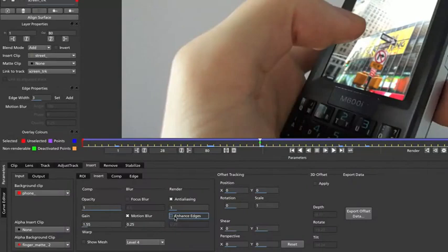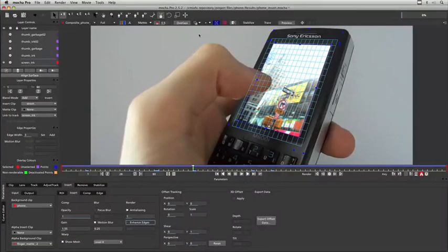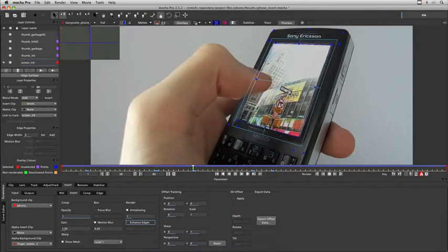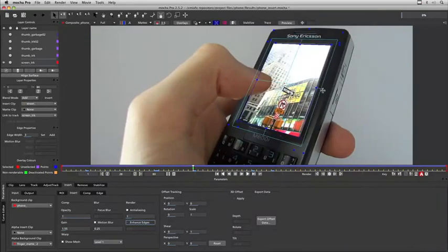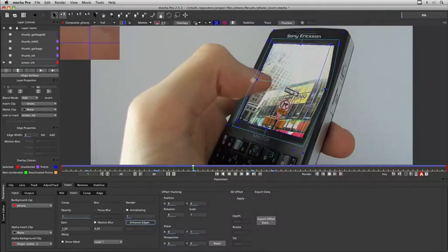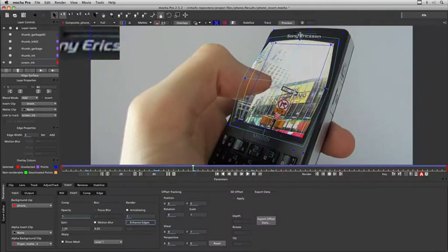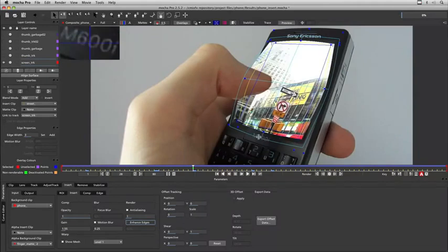And the last attribute that we have here is the warp. To understand the warp, I need to turn on the overlay. And the warp is basically a mesh warp that provides you 4 levels of distortion to use. The usage is very simple. Just drag the warp points to create the deformations, and the edge points are very useful to match surface borders that are not exactly straight lines. It is a very handy tool, and it will follow the surface movement. So let's take a look.